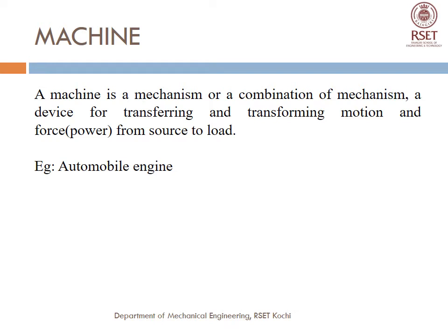There are some other mechanisms which are interlinked or connected to this mechanism to form the complete IC engine, or the complete machine. The best example is that inside a cylinder there will be two valves, that is the inlet valve and the outlet valve. The opening and closing of these valves is controlled by the camshaft, in which there will be cams. Cams will be connected to the inlet and outlet valves. So this opening and closing is controlled by the motion of this camshaft.